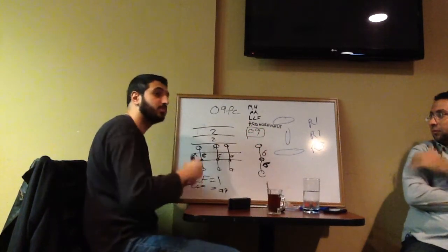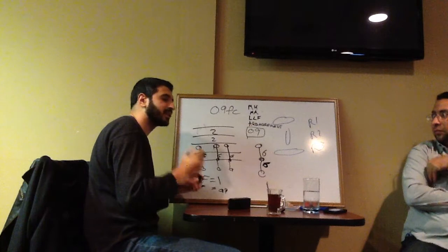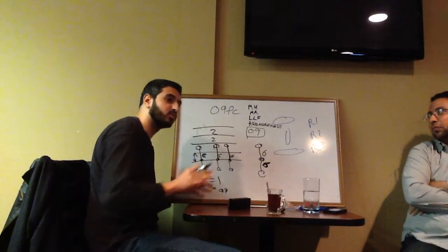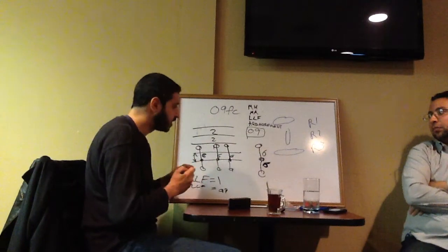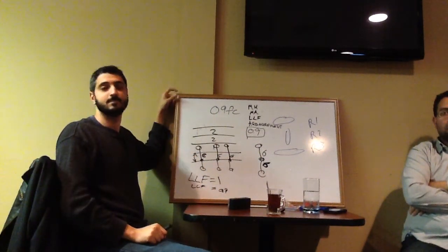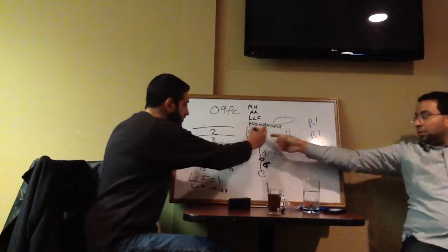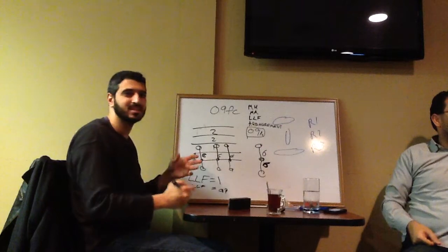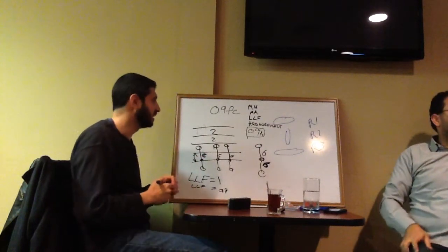It also has the minimum, the maximum, and the average to minimum, which is the uniformity of light distribution. Not to confuse this 0.9 with the LLF, this is the foot-candle. The LLF is a ratio, so it has no unit.